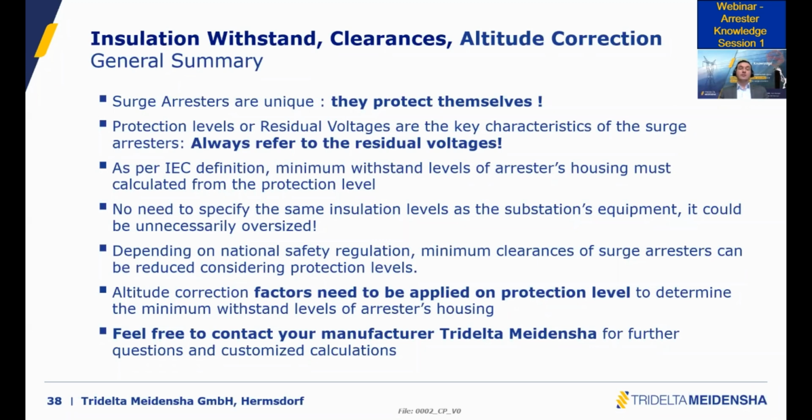The altitude correction factor needs to be applied on the protection level, including coordination factors, to determine the minimum withstand level of the arrestor. So if you have any concrete case, you can contact us, and we will try to support you in this calculation.